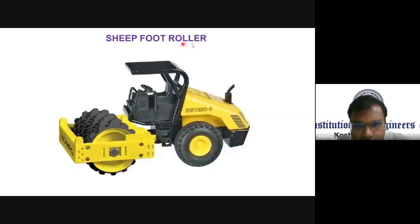This is the sheep foot roller. You can see how it looks. And the advantage here is that it can go up to 25 kilometers per hour. In the case of the smooth roller we saw as the first type, with a single roller at the front and two rollers at the rear, the depth is not that effective. But here you can go to a higher depth, and the compaction efficiency is also higher.